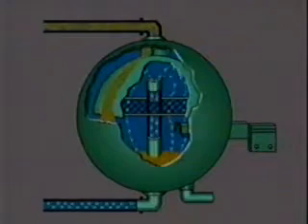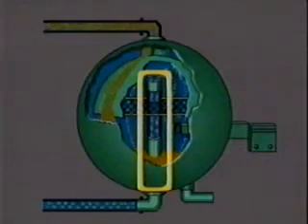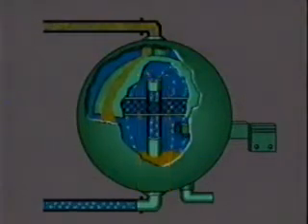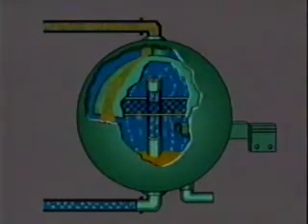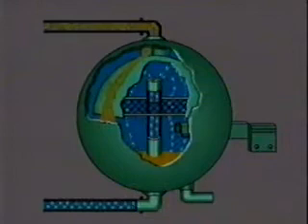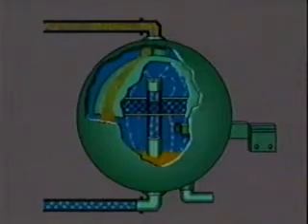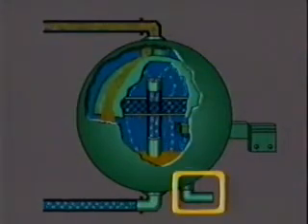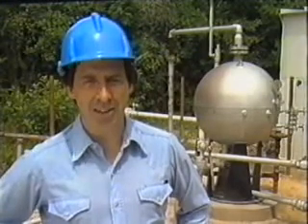Liquid droplets collect and fall downward. Gas leaves the vessel through a vertical pipe above the mist extractor. Notice, unlike the other separators we've discussed, the gas outlet in the spherical separators is at the bottom of the sphere. While liquids accumulate in the bottom of the sphere, gravity settling causes solids and some water to collect at the bottom of the vessel. Liquid leaves the vessel near the bottom of the sphere, controlled by the liquid level controller. Spherical separators offer advantages of compact size and good gas handling. In our next category, we'll examine three-phase vertical separators.